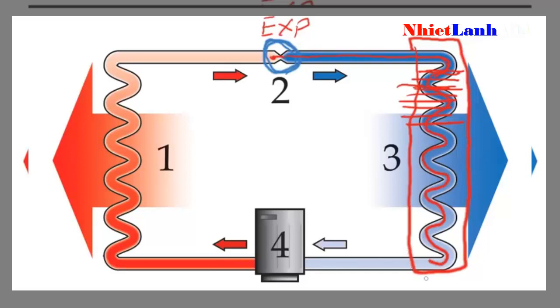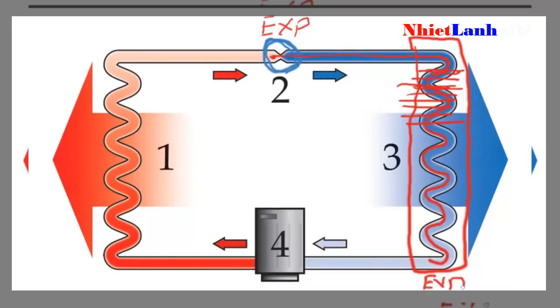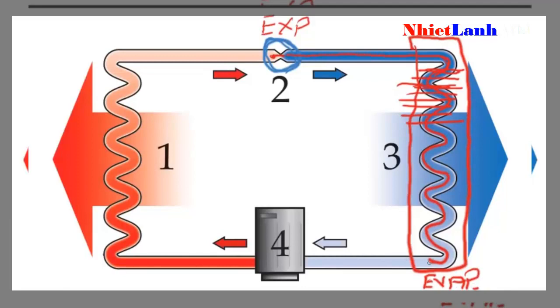So this is our evaporator coil, and the gas exits this evaporator coil and it's picked up all of this heat. So it's a gas. This line will feel cold to the touch, but it's a gas and not a liquid. So it's entering the compressor, and basically a compressor is either a piston type pump or some type of a scroll positive displacement pump, and so many times you'll hear this copper line referred to as the suction line because it's going into the suction side of the compressor or pump.